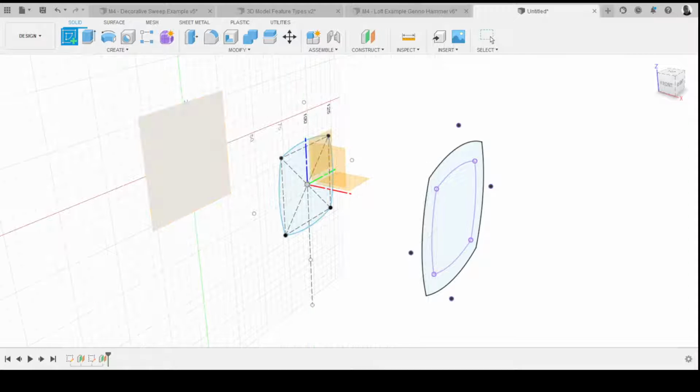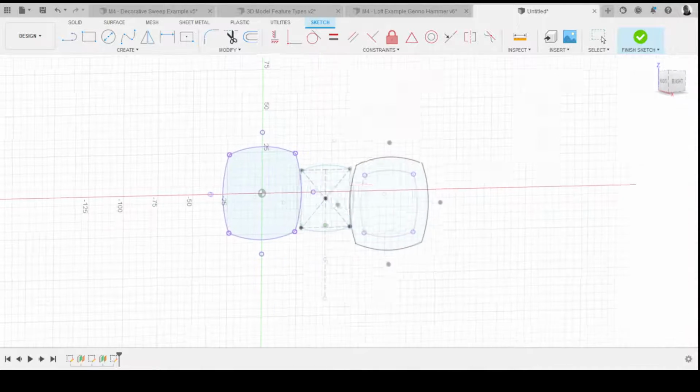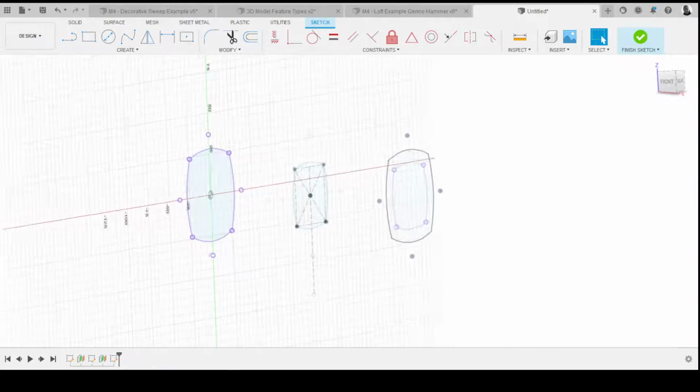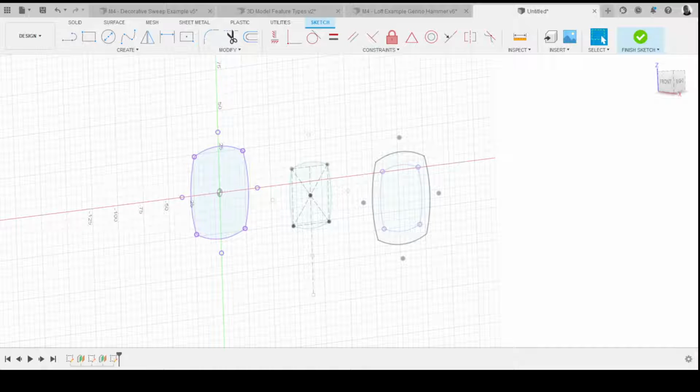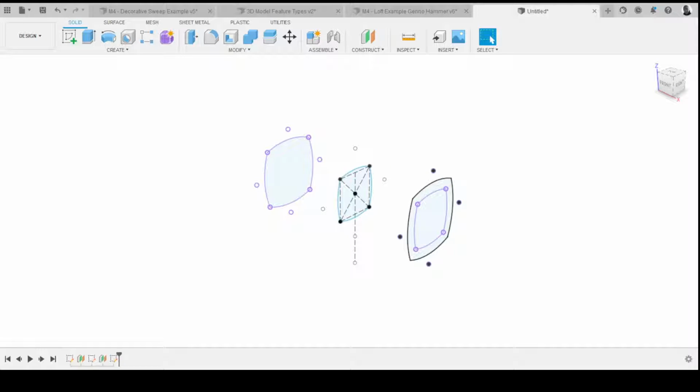And create a sketch on the plane we just created. And again, we can just project that bigger sketch we've just done. So if you go to P on the keyboard, project, those four, click OK. We've now got that mirrored sketch. So very quick and simple to do. We're just using that one sketch we created in the first place and using it again by projecting it and offsetting it, if that's what your design needs you to do. It depends on what you're designing.